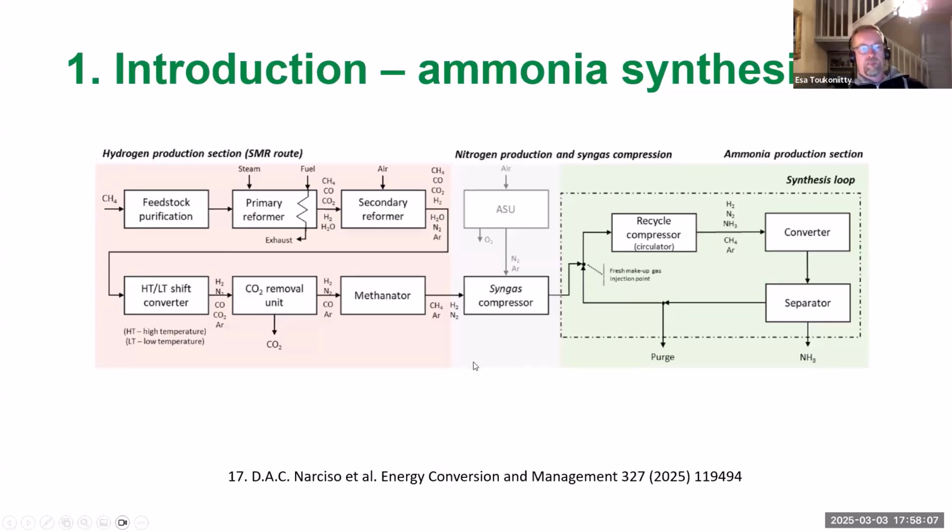And here in the second part, there is compression of the syngas, and the actual ammonia synthesis chemical reaction happens in more or less the second last step of this block diagram. So what is fed into the converter? Hydrogen, nitrogen, and the recycled ammonia and gases.